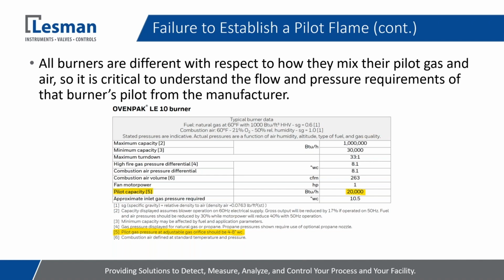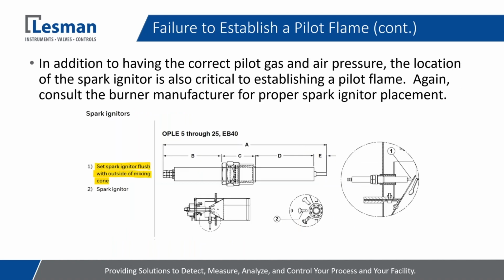So it's important to know exactly what kind of pilot that you're working with, how it interacts with the burner, and recommendations of the burner manufacturer, right? This will allow you to make the adjustments as long as they're within the spec from the burner manufacturer to give you the best chance for success.